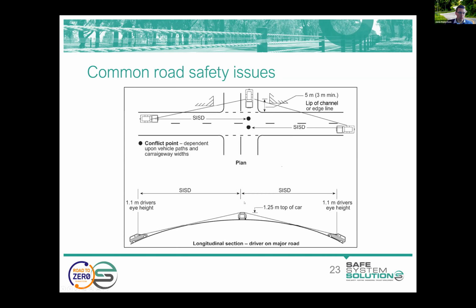It might be to the pavement. It might be to an object on the pavement as per SSD, stopping sight distance. In some situations, we might measure from an eye height to a tail light, a brake light or a headlight, so that a motorist can see that part of the vehicle and react to a brake light perhaps.